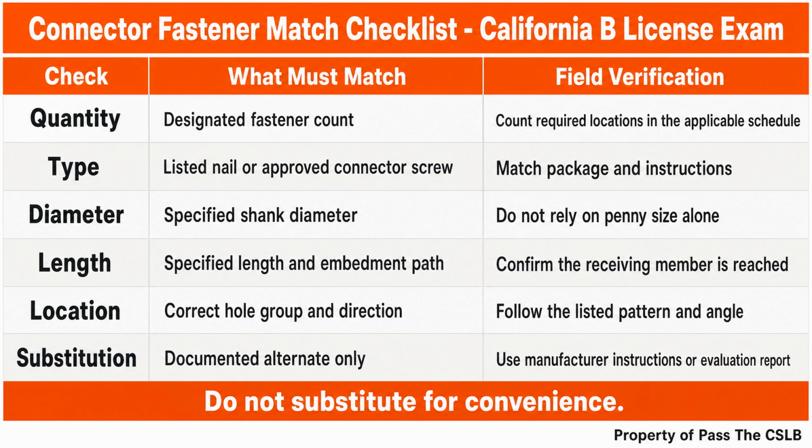On a busy framing job, nail heads can make this harder. Once the nail is driven, the supervisor may not have an easy view of its full length or shank. That is why control starts before installation. Verify the exact carton, keep incompatible fasteners out of the same work area, and confirm the tool is loaded with the approved product. After installation, use the head markings, packaging, and manufacturer guidance that are available for verification.